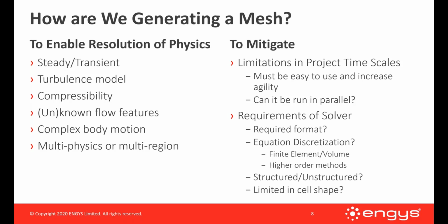effectively? Next, we need a meshing approach that mitigates the requirements of a solver. Does a solver have a specific format? Does it discretize these transport equations in a specific way, meaning finite element or finite volume, or do we need a way to generate higher order meshes to be able to use a higher order method? Is the solver limited to a structured or unstructured type mesh? Are there limitations in cell shape? So a mesher needs to be able to inherently overcome all of these types of requirements.